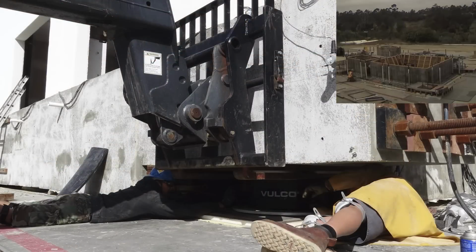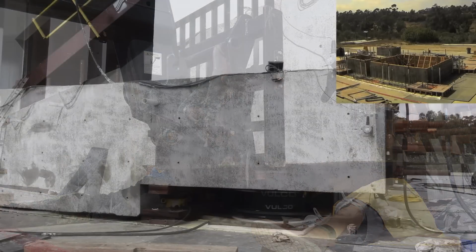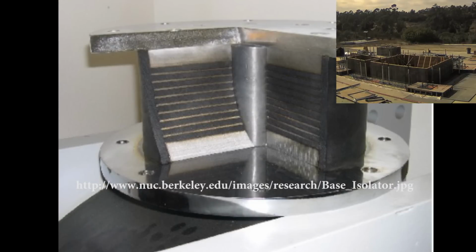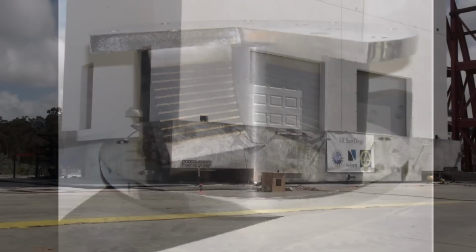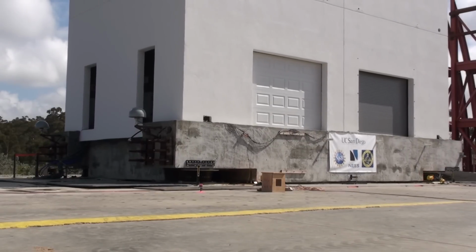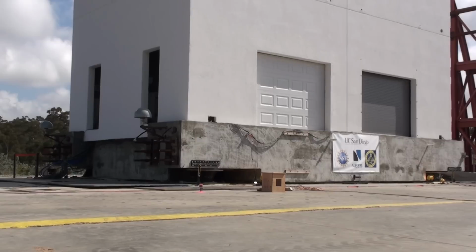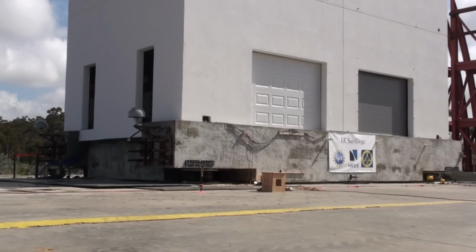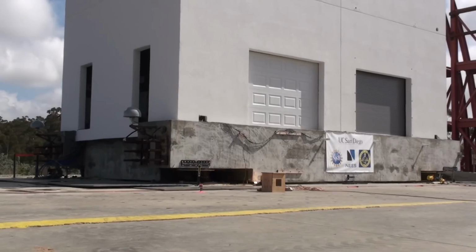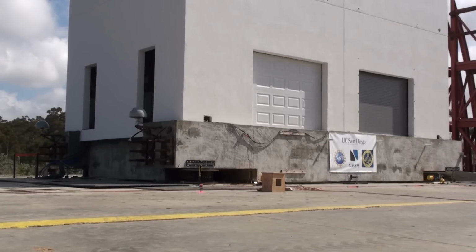In this project, 4 high-damping rubber base isolators were placed under each of the 4 exterior columns of the building. These dampers were cylindrical in shape and consisted of layers of rubber sandwiched between plates of steel. Base isolators are very stiff and strong in the vertical direction, but flexible in the horizontal direction. When an earthquake occurs, the accelerations transmitted to the building is reduced and the building's natural period of vibration elongates. As a result, the isolation system can absorb more than 80–90% of the displacements imposed on the structural system, and interstory drifts, which, if large enough, can be damaging to the structure and its non-structural components, are significantly reduced.